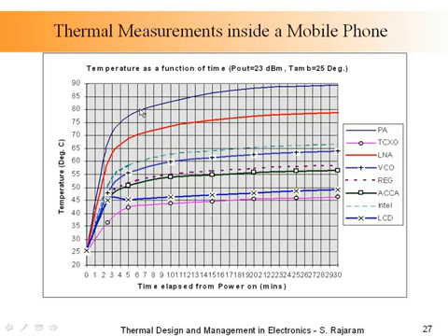In this particular case, you can see the power amplifier on the phone is reaching 85 degrees to 90 degrees. And in fact, the users were complaining that it was heating their ears, and they were complaining of not being able to touch the surface. This was actually a problem because of poor thermal design, and this product was redesigned.